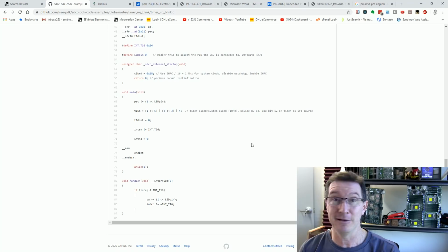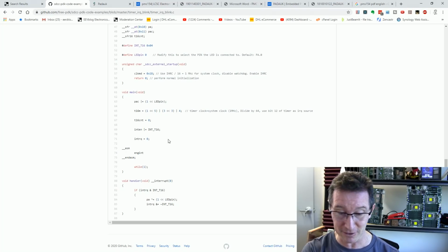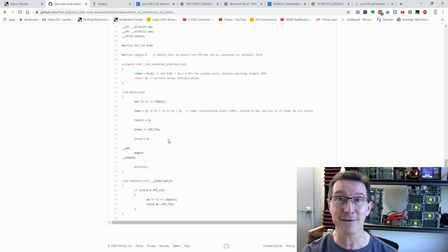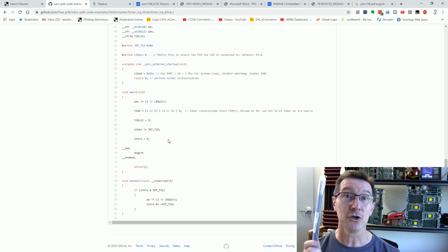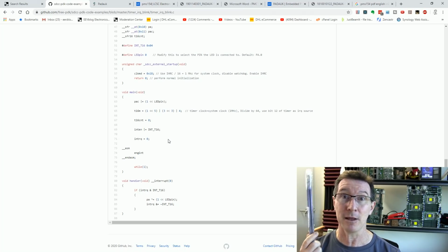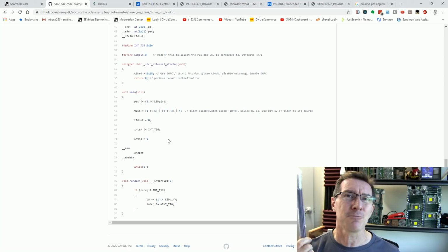But hey, it takes me like a minute to compile this and program a new chip. And I've got lots of chips, even though they're one-time programmable. I've got a few. So, yeah, we can afford to do this. And that's the thing. Even though these aren't flash, these are so cheap. They're 3 cents a pop. So you can actually afford, I know it's like a waste, but you can actually afford to refine your code like this. And once you get it perfect, even if you have to go through 50 of these things to perfect your code, bingo, it's set in stone, because these programs aren't big.